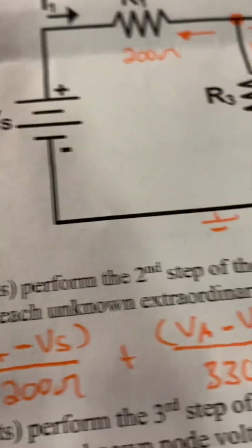And then at our voltage source, we are getting 10.06 volts. And that's what is reading there. And then to measure our current, we must break the circuit, which I will do.